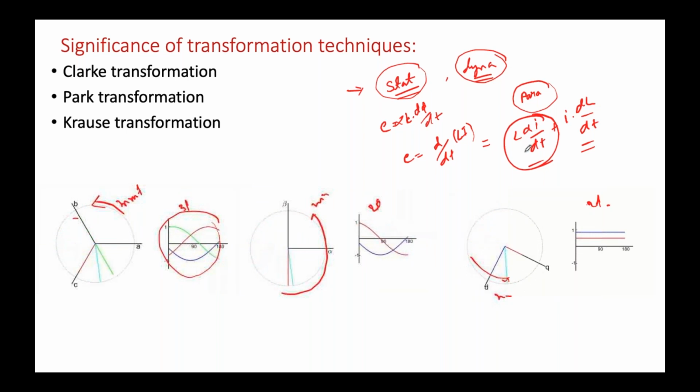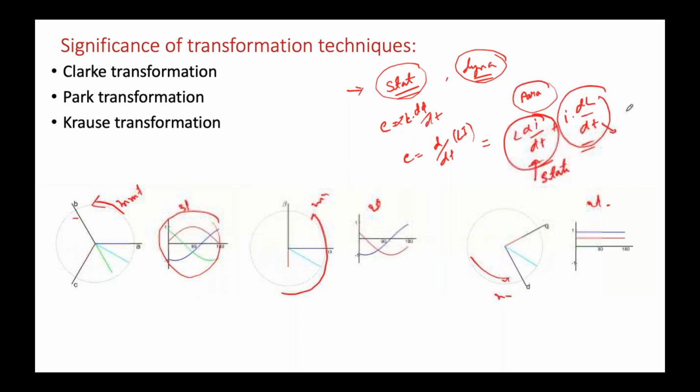That's what I'm telling: how we can differentiate. I have already given a hint. The mathematical expression is already there. Now think. This L di/dt is the self-induced EMF. The second one, is it static or dynamic? It's static, sir. L is static. Yeah, L is fixed. The second one, inductance is varying, so that one is dynamically varying. Dynamic.